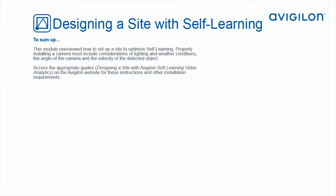To sum up, this module overviewed how to set up a site to optimize self-learning. Properly installing a camera must include considerations of lighting and weather conditions, the angle of the camera, and the velocity of the detected object. Access the appropriate guides on the Avigilon website for these instructions and other installation requirements.